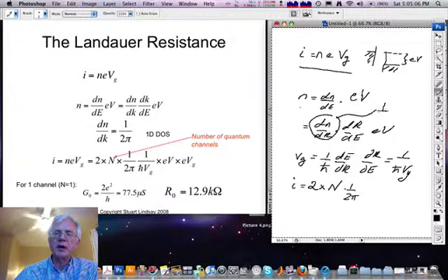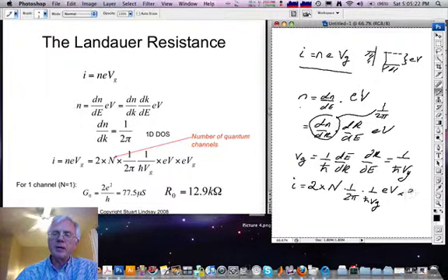This was a result we derived in chapter 2. Then dk/dE was 1 over h bar vg, times this energy range, the electronic charge times the bias applied, times e, and times vg. Look at what happens here. vg is the one material-dependent parameter here. It's the group velocity, which depends on the curvature of the bands in the state allowed into the channel. This disappears from the expression for current.